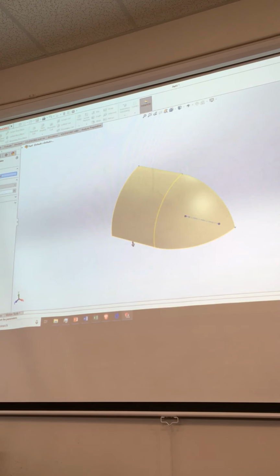Because I think if I had 4 of those around, I'd have a half a pressure vessel. So 1/8 of it, not 1/8 scale? No, it's not 1/8 scale, 1/8 of it. Okay. And we only need to model 1/8 because it's a pressure vessel and we have symmetry.